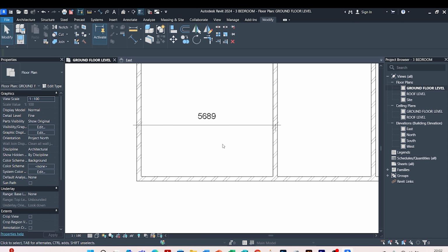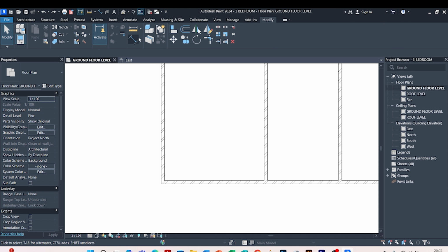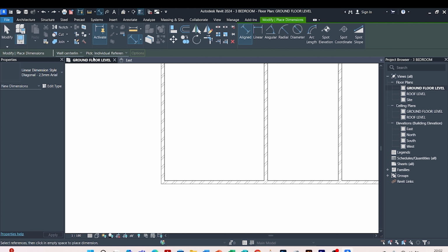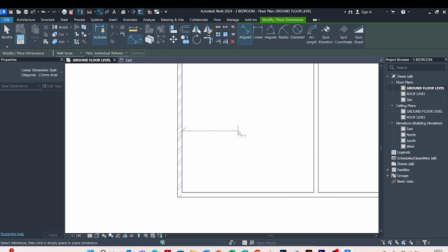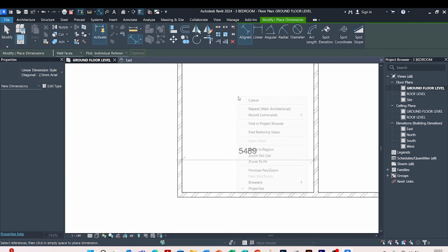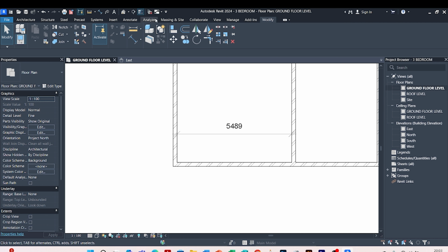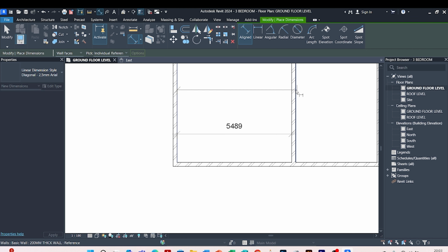So what do I do? I click on it. The reference, you come here where there is wall center line, you drop down, you pick wall faces. So we shall pick this from there up to here for the wall faces. Or if you don't want to, just come to this align dimension tool, you just click DI, then it activates dimension like that, so you can dimension.